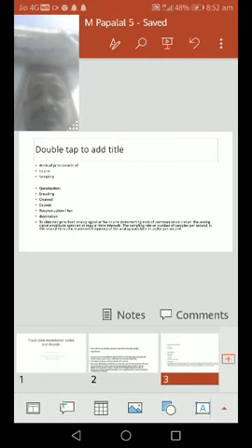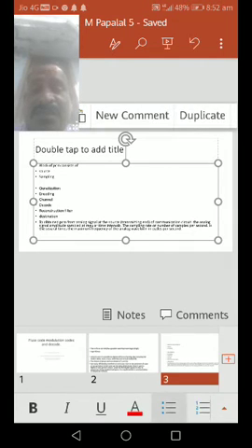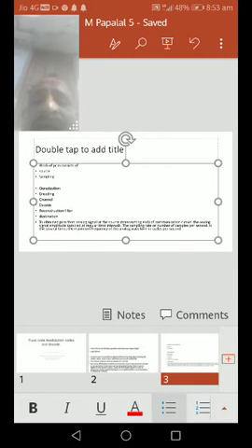Basically, the PCM blocks consist of the source and sampling. The first stage is the source, the second stage is sampling, the third stage is quantization, the next stage is encoding, and the next stage is the channel. After that we have to decode the signal and reconstruct the filtered signal, and it reaches the destination.